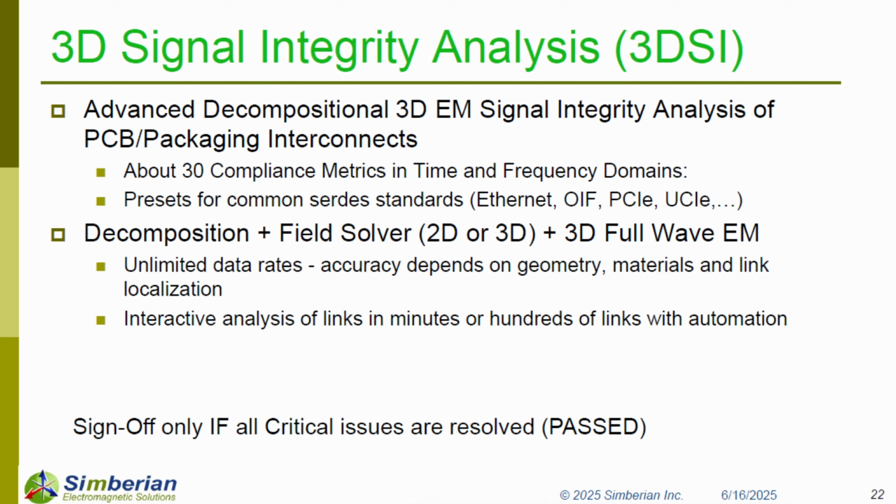And it uses 3D full wave models for vias, most important, and for other discontinuities. Technically, it has unlimited data rates, but accuracy depends on geometry, material models, and localization. And we checked localization at the first step with ERC. In this case, localization is sufficient pretty much everywhere. There are a couple of violations, but we'll see how it goes.